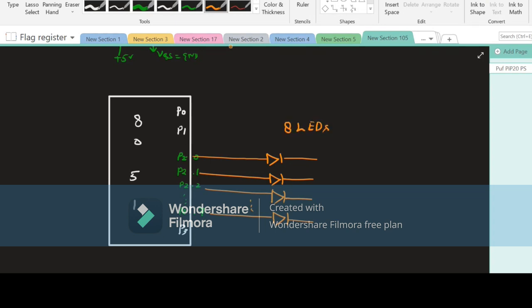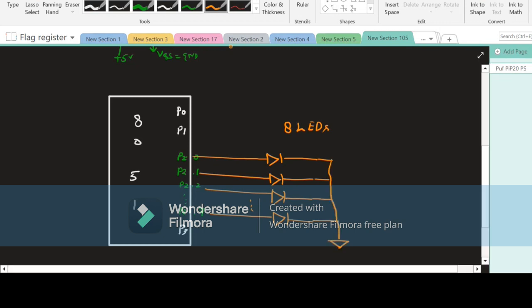So now I am going to tell you the generalized program. If in the question it is asked to use 2 LEDs, or 3 LEDs, you can use those. But I am going to give you the generalized solution for 8 LEDs. All these LEDs can be connected to port number 2 because there are eight pins, and the other end of each LED is connected to the ground. That's it. Now what happens, sir?